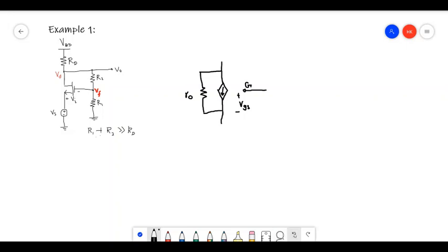Now I'm going to connect other things. For the source terminal, this voltage source Vs is going to connect there, and ground it here, and the output will be taken from the drain, and also this RD connects to the drain. Since the voltage source VDD will be grounded by short circuiting in the small signal model, I can have it like this.